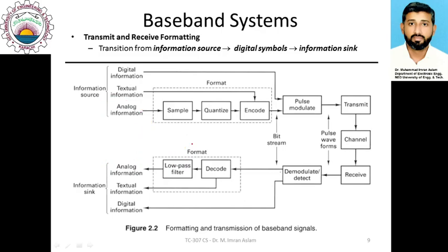So you can see that in this way we generally achieve digital transmission for baseband systems. Similarly, if we need to incorporate a band pass system, in that case we need another block where we incorporate the sinusoidal carrier, and that sinusoidal carrier generates the band pass signals so that they can be transmitted through the channel.